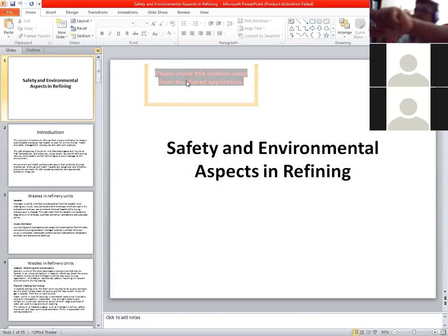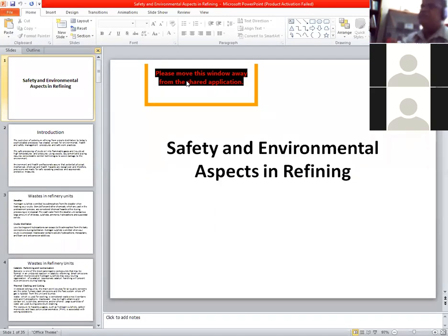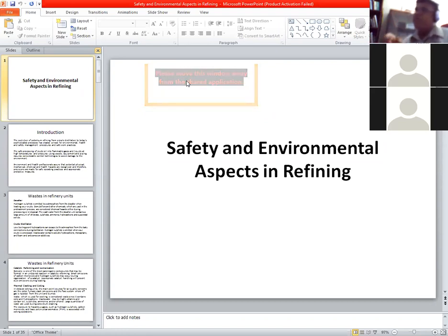If, for example, you are doing some activities like maintenance near the tank, or due to some reason the outside temperature increases, then definitely the temperature inside the tank will also increase. If the temperature increases above the boiling point temperature of that particular liquid, that liquid will expand and its volume will increase. Ultimately, due to an external source of fire or heat, it can explode.